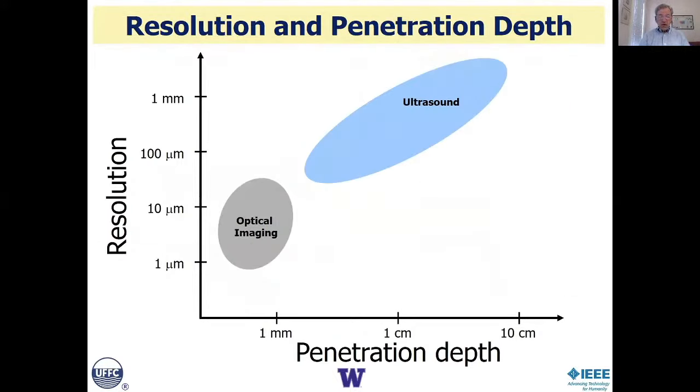So what the photoacoustic effect does is span the worlds of optical imaging, which is typically in millimeter scale penetrations, but down in micron scale resolutions, up to the ultrasound world, which is in centimeters and tens of centimeters even in penetration, but resolutions in the hundreds of microns to millimeter range. Where photoacoustics works is spanning this range, because we have the optical penetrations, which are typically a few centimeters, nowhere near as much as in ultrasound, but still for many applications useful.